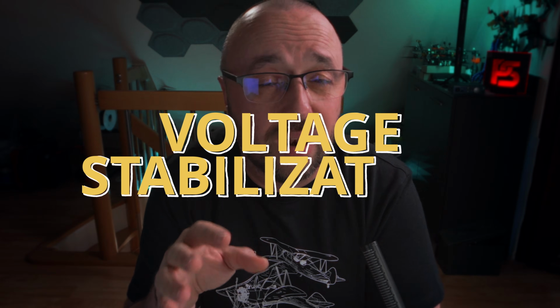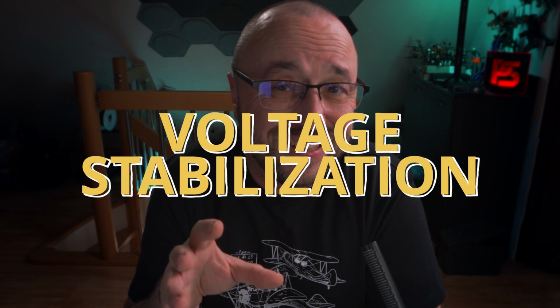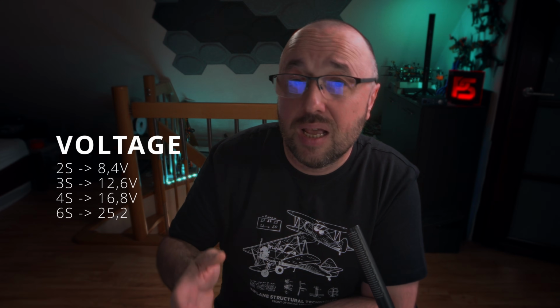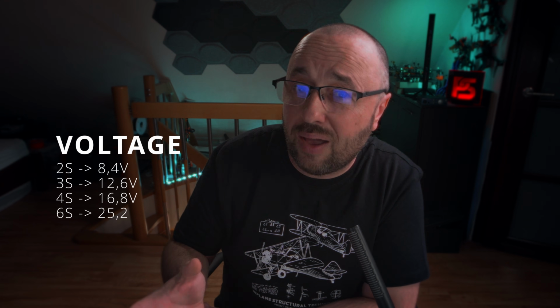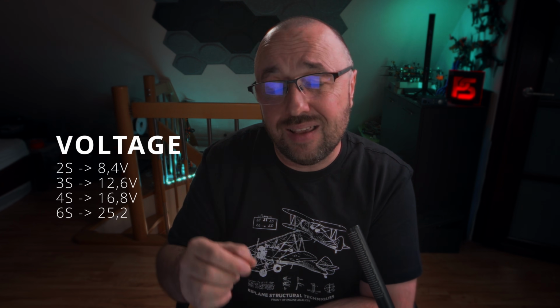And finally, the last required element is the voltage stabilization. Currently, we like to power our airplanes and drones from relatively high voltage, 14, 16, maybe even 20-something volts, while the whole electronics run on 5, 3.3 volts and even less.